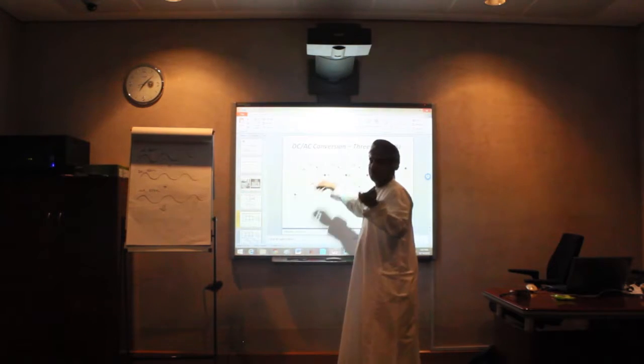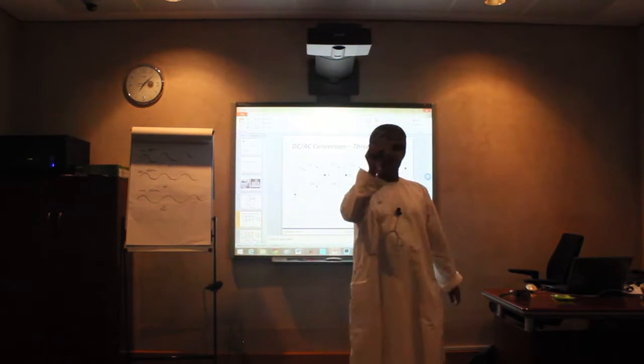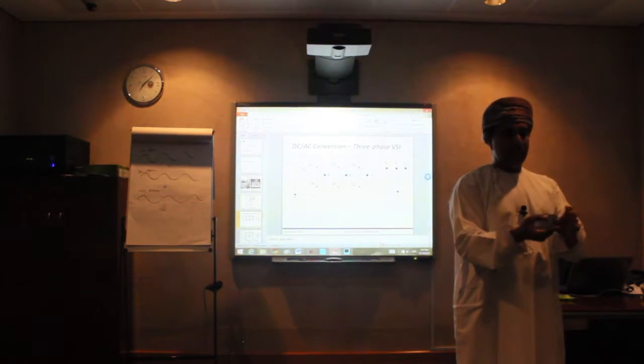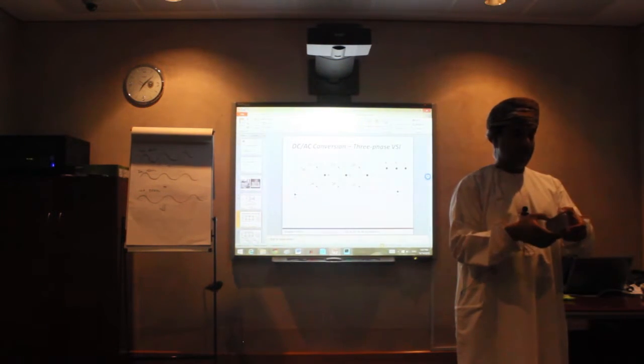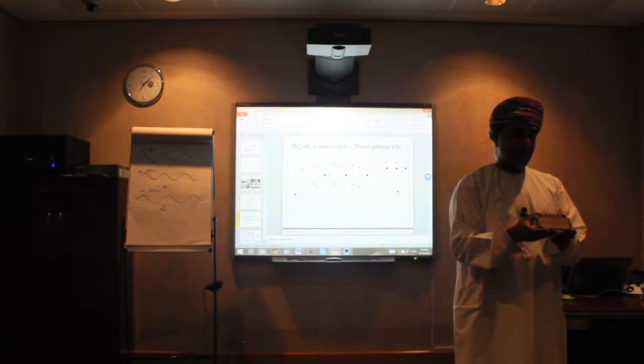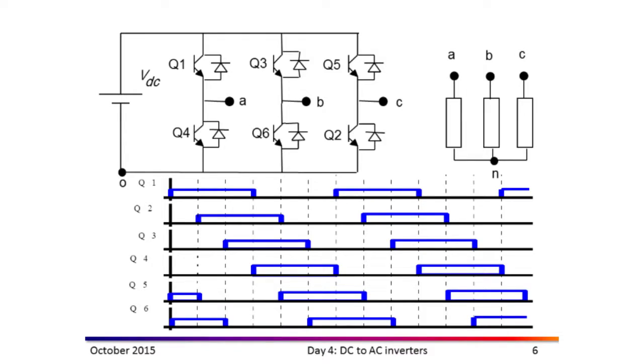in addition to the control and input and output. So you can use a chip like this, okay? And the rating of this one, if you look at the rating, it can afford 1,200 volt, and you can use it up to 100 ampere. So that means you can design an inverter on that one. Just connect your inputs and output and make an inverter through this one.